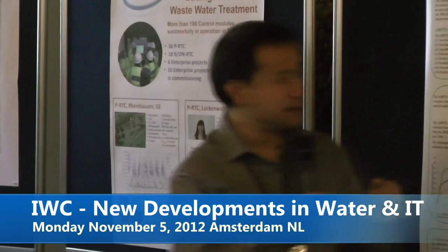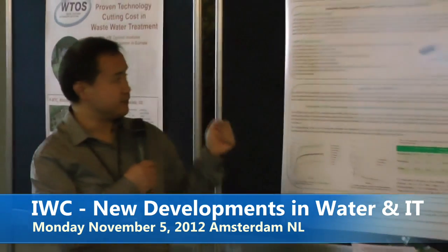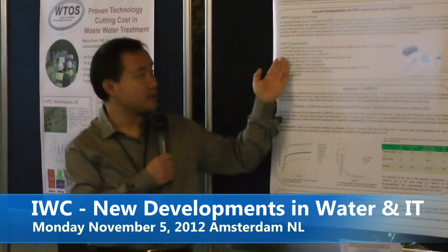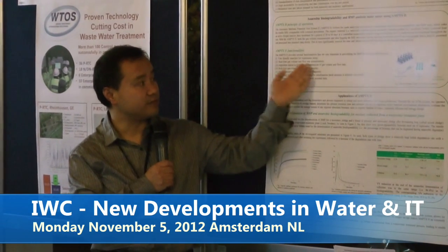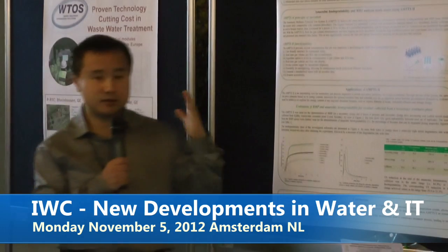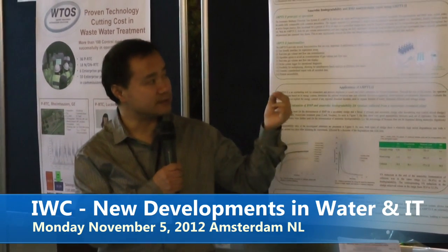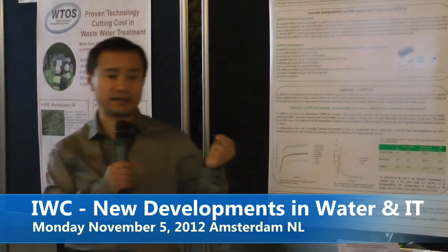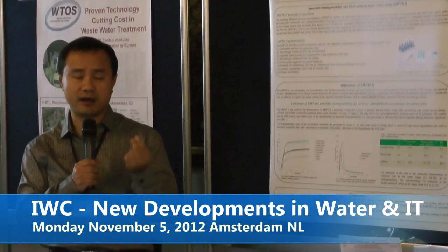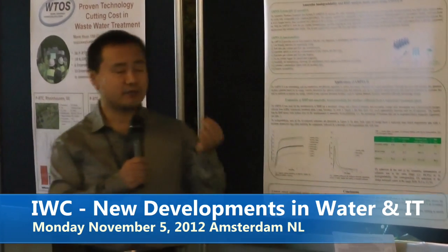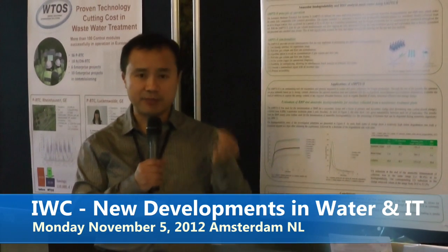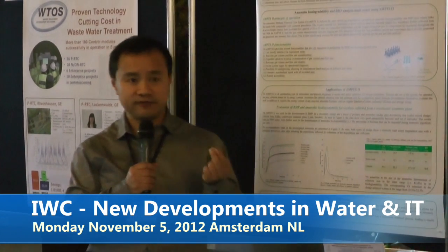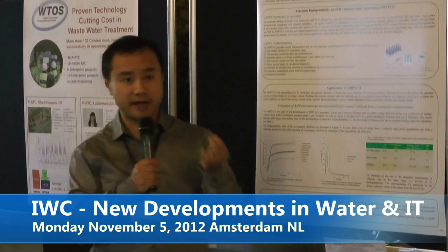And what we have presented is a case where AMPTS has been developed to basically solve those issues. Basically, we are talking about a more friendly user interface for experiment setup, more real-time gas volume and flow rate normalization, because you know that the key parameter for this BMP test, or anaerobic biodegradability, is to monitor the ultra-low gas flow. And when we measure the gas flow and the gas volume, temperature and pressure have a big influence on the measurement accuracy.